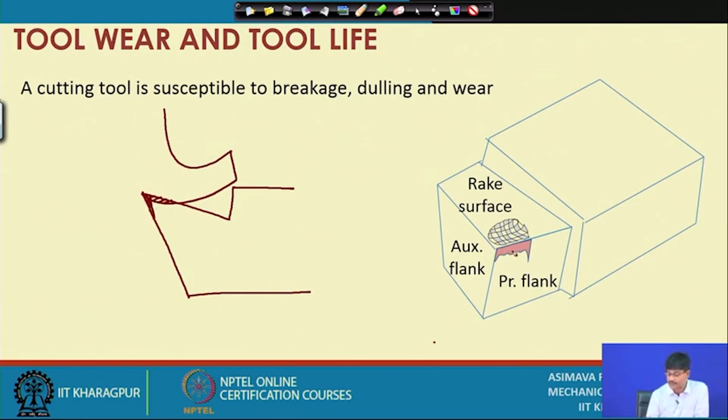So, the principal flank is undergoing wear, where you can see there is a large notch at the side, because that is where the end of the chip is moving and it is having an edge. Edges always create a high amount of wear. So, this is the rubbing action of the edge. Here also a sort of edge will form, edges like these.